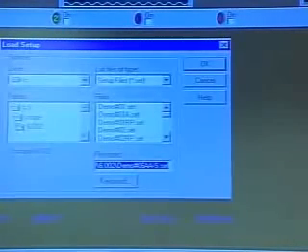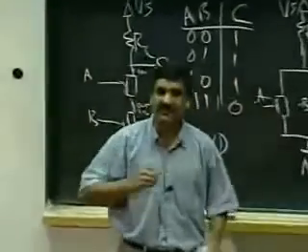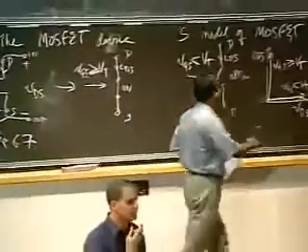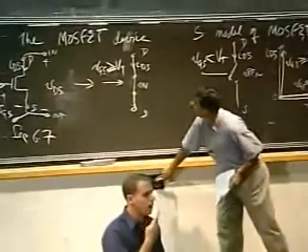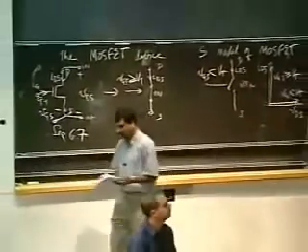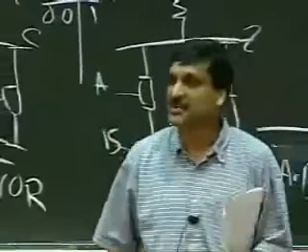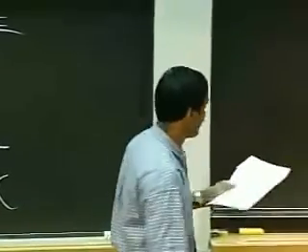Okay, I'd really like to think of this pressure analogy if I get confused. Whenever I look at a MOS transistor and I need to look at VGS and so on, I always think, when VGS is greater than VT, lots of pressure on a switch, it turns on. Just remember that, and then you won't forget this VGS thing here. So that's the behavior of a switch, and so voila, there's our switch. Okay, so I've given you a 3-terminal element that is a switch that is controlled like a mechanical switch.